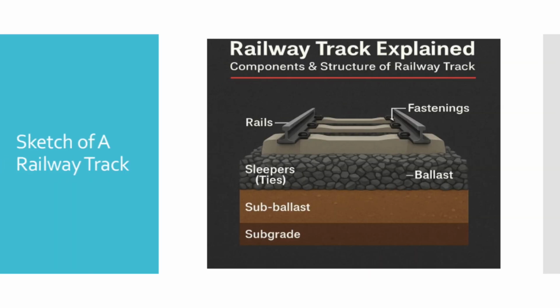If I show you with my pen, these are the ballast, these were the sleepers, and beneath that is the ballast portion. Okay, I hope it is clear. It is made up of gravel. Nowadays we see that this ballast made up of gravel is laid below these sleepers, around and beneath them. So no water is absorbed, everything is drained. Also, it keeps the upper portion in position and distributes the load evenly.